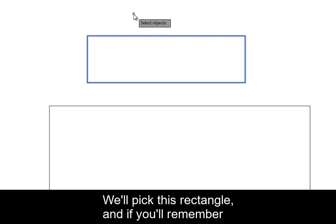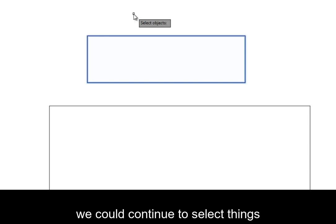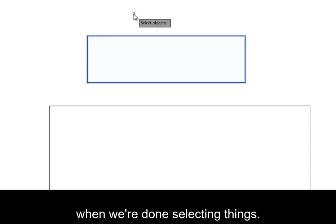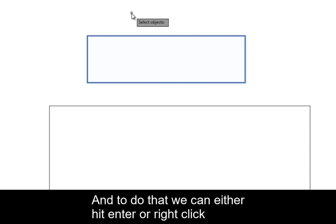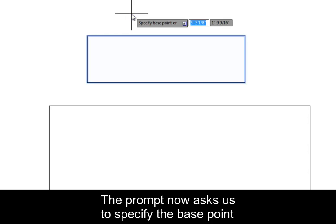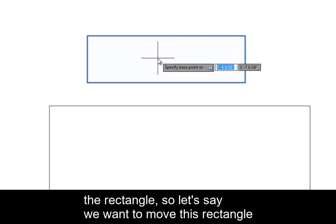We'll pick this rectangle. And if you remember from the last video, in our selection options, we could continue to select things. So we have to be able to tell AutoCAD when we're done selecting things. And to do that, we can either hit Enter or right-click on our keyboard. The prompt now asks us to specify the base point. So this is the point from which we wish to move the rectangle.